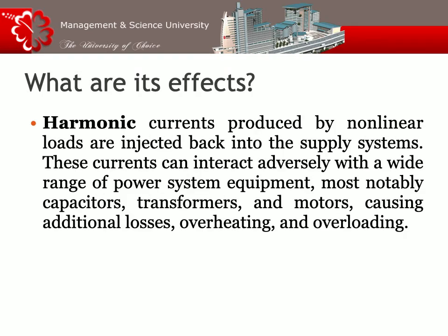What are its effects? The harmonic currents produced by non-linear loads are injected back into the supply systems. This current can interact adversely with a wide range of power system equipment, most notably capacitors, transformers, and motors, causing additional losses, overheating, and overloading.